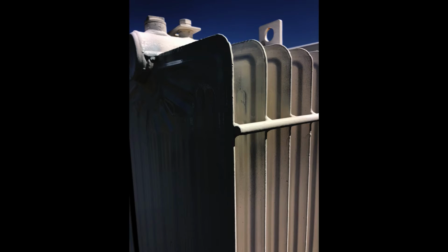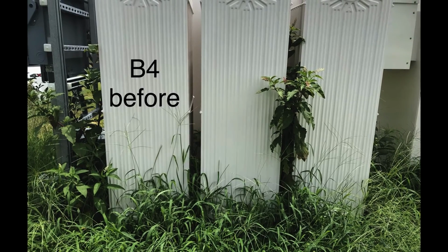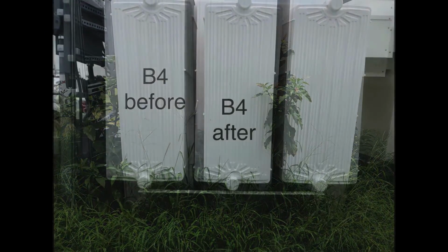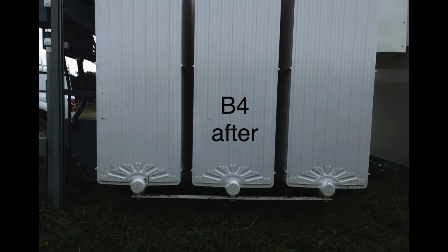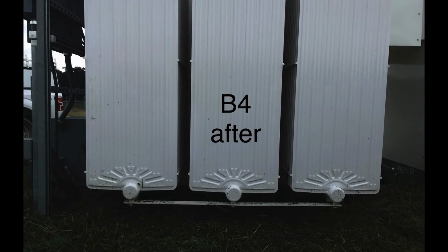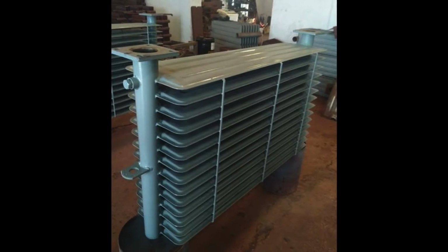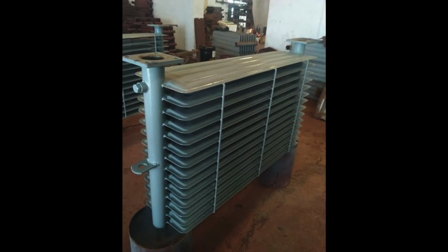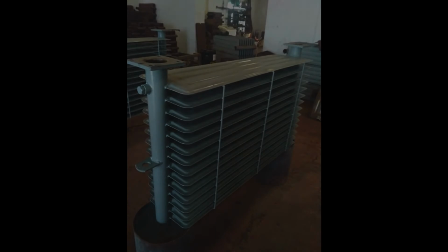The radiator dissipates heat from the coolant via convective flow. Most PV transformers use entirely passive cooling, where the coolant flows through the radiator via convection, and air moves across the radiator passively, as opposed to either pumping the coolant or blowing the air with fans. The headers of the radiator are flanged directly into the tank and will have a drain plug on the lower header and a vent plug on the upper header.